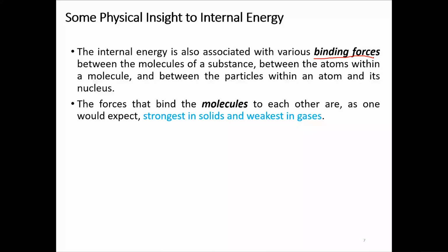So the energy related to the phase change of the system, that means the energy required to overcome the binding energy of the molecules in order to convert it into another phase, that is the phase change energy part of the internal energy. So internal energy has the sensible part, which is related to the kinetic energy of the molecules. The other part is associated with the phase change of the system. Clear enough? Is this part clear?